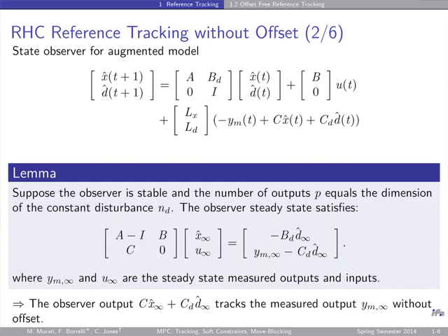And this determinant has in here BD, since CD is equal to I, and so this condition tells me how I can choose BD. I can only choose a BD such that this matrix here has determinant not equal to 0. That's my restriction. Once I select CD equal to I, a simple disturbance at the bottom, I have to select BD such that this determinant condition is satisfied. That is a restriction on my disturbance model, how I can choose the disturbance to affect the states.